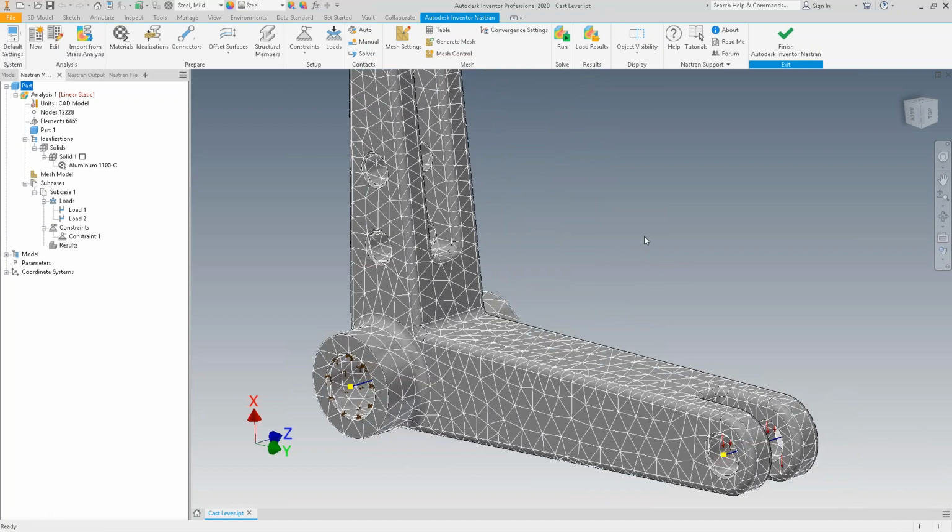Those make sense. Looking at a flat face like this, if you suddenly see a change in the mesh, there's a topology problem with your model. Now, we could be working with a downloaded model. Could be a downloaded pillow block that's crucial to our design, or downloaded bracket. That's typically where we'll see issues like that, not necessarily with something that's natively created in Inventor.